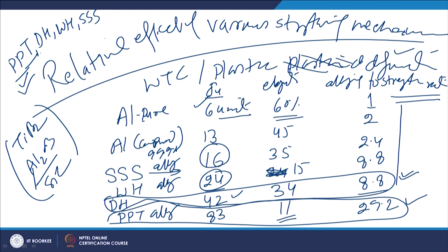Similarly, if there is a loss of the dispersed constituents, either due to fracturing or their dissolution, then these will cause a further severe loss of hardness. Thereafter, the loss of the work hardening effect due to recovery and annihilation will again lead to a reduction in strength and hardness. Minimum effectiveness is there for the solid solution strengthening.